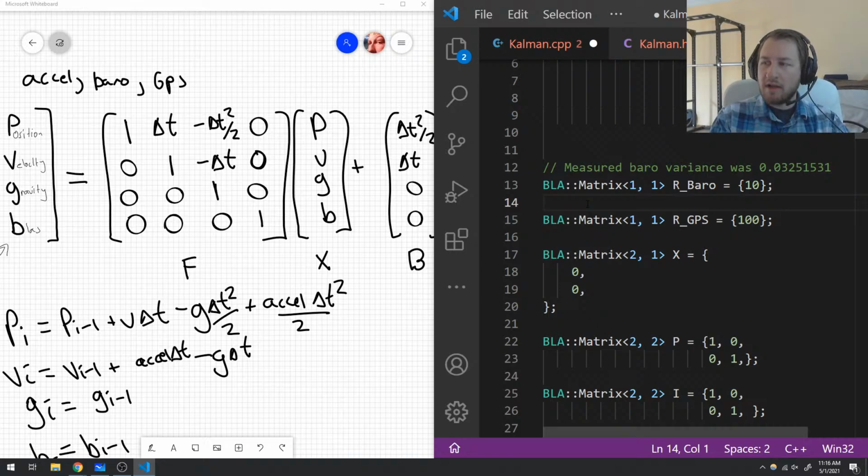So we don't want the Kalman filter to wait for the GPS in order to update with the barometer and the GPS. We don't want to go as slow as the GPS does. We want the barometer to update the Kalman filter anytime it can, and the GPS to update the Kalman filter whenever it can. That's why we split these apart into separate measurements.